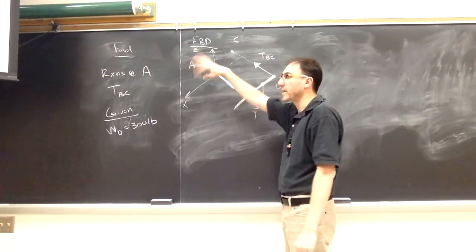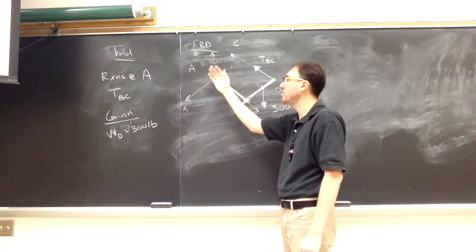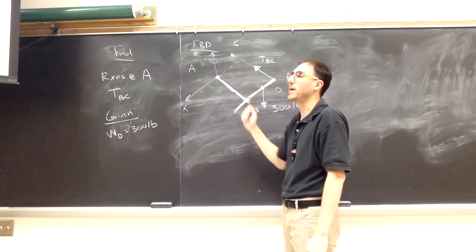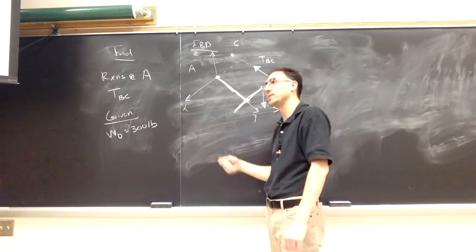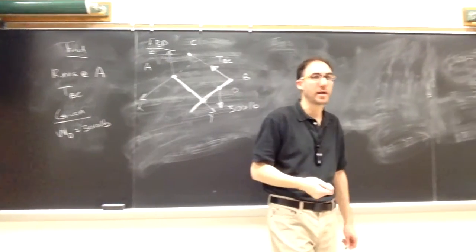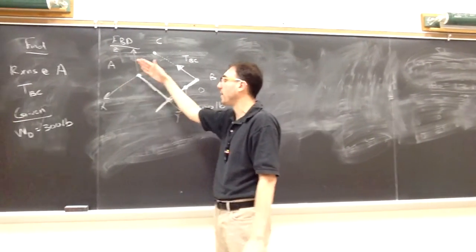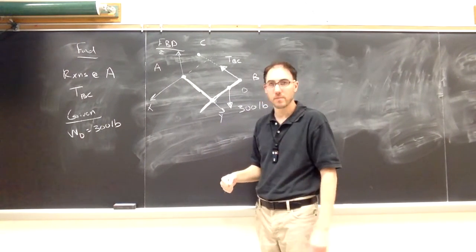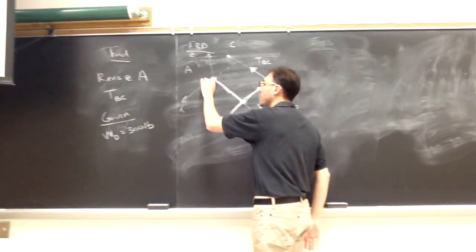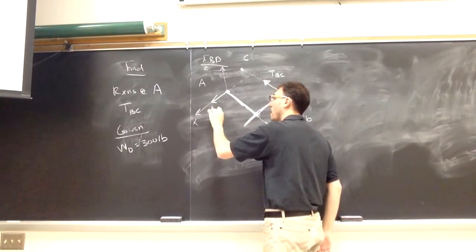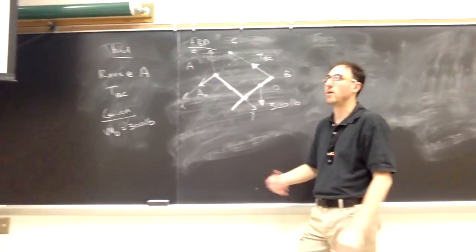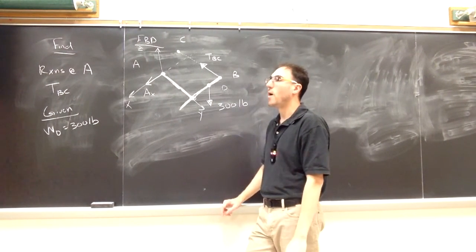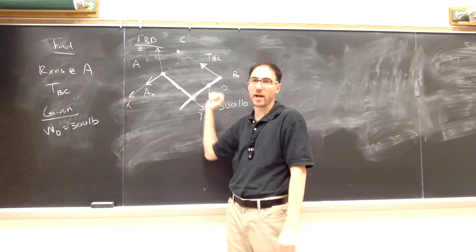All right, so generally we can think of it in the X, the Y, the Z directions because usually it's oriented that way. But really we can think of, does the pin allow translation, or what translation does the pin prevent from happening? Along the x-axis, can we move it left or right because it's connected to that pin at A? Right, we can't move it, so I can include a force because that motion is prevented. I'll assume it's along the positive x-axis. In the y direction, can we move it along the y direction because it's pinned?